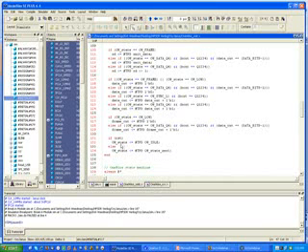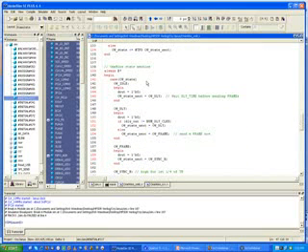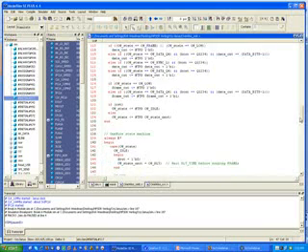Here we go. When we're in reset, the state goes to idle, okay? And then the OW state next is based upon the state machine. So in the state machine, we're in idle to begin with, and we stay there as long as we're in reset, and then the next state becomes OW delay, which is a value of 1. And then the next one after that is OW frame, which is a value of 2.